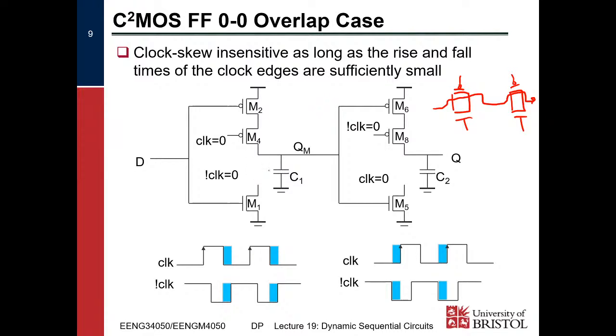However, with this circuit, we'll see that it's actually not going to happen that way, because our PMOSs are only driving 1s and our NMOSs are only driving 0s. So we can't have the case of an NMOS driving a 1 as a pass transistor or a PMOS driving a 0 as a pass transistor. So we'll assume that we make a change on D and it propagates.